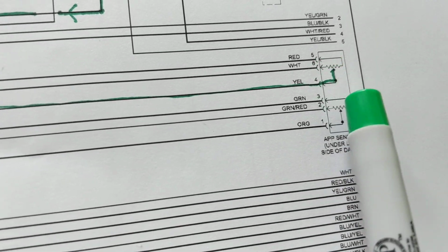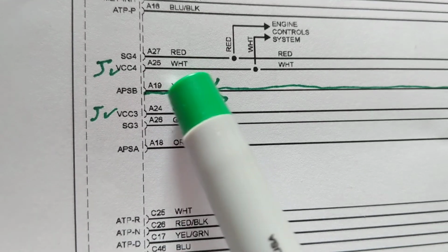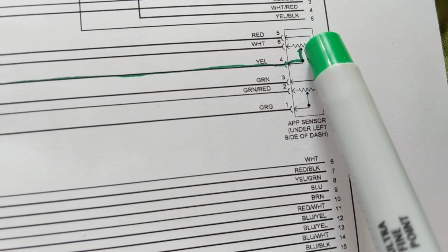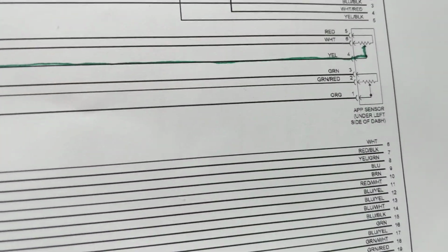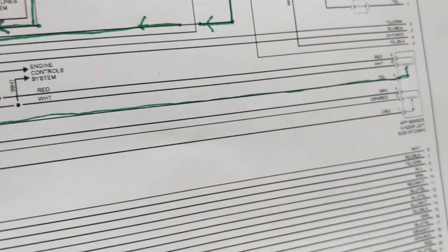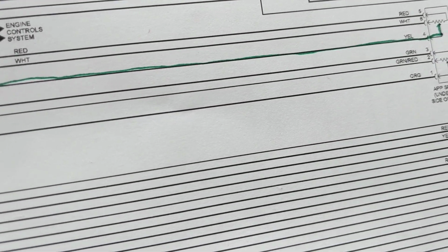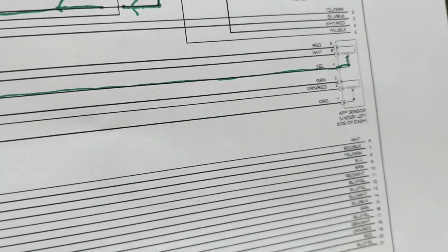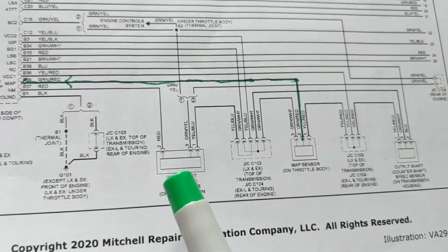As you notice, we have a ground, and we have a VCC also over here. VCC is another word for the main B plus voltage. So we have two of them over here. They both work the same, but if one fails, the other one works. You don't want to lose control of the gas pedal. With some makes and models, if there are no sensors working for that gas pedal, you won't be able to start the car. That's a dangerous situation, isn't it? So it'll shut it off and you'll get codes for it.